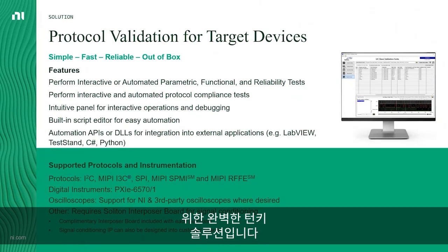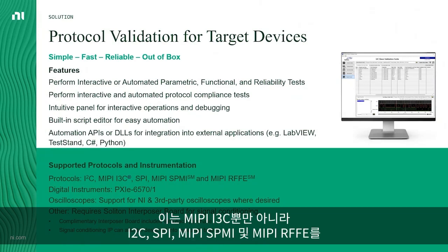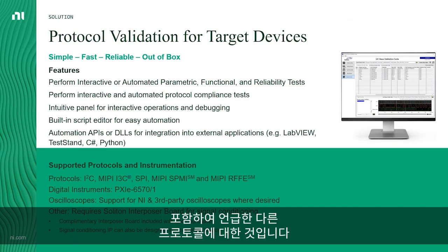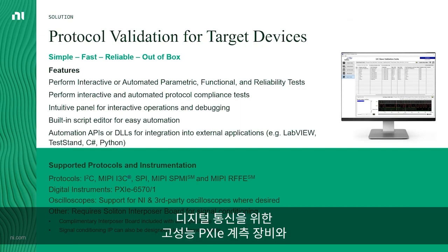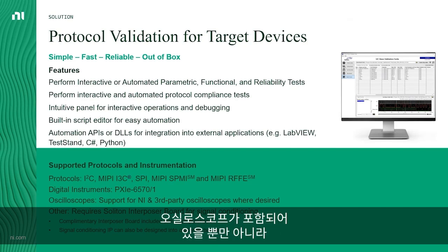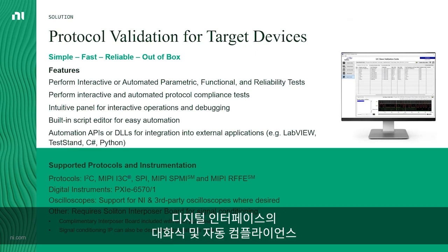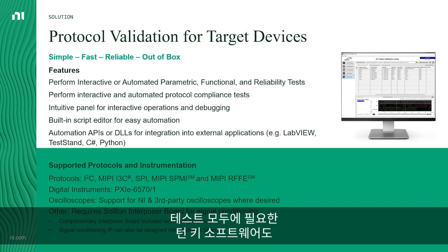All right, thanks, Saravana. To wrap things up and summarize, what you've seen today is a complete turnkey solution for protocol validation of target devices. This is for not only MIPI I3C, but also some of the other protocols we mentioned, including I2C, SPI, MIPI SPMI, and MIPI RFFE. It includes high-performance PXI instrumentation for digital communication, and even oscilloscopes for the additional measurement types Saravana mentioned, as well as the turnkey software needed for both interactive and automated compliance testing of your digital interfaces.